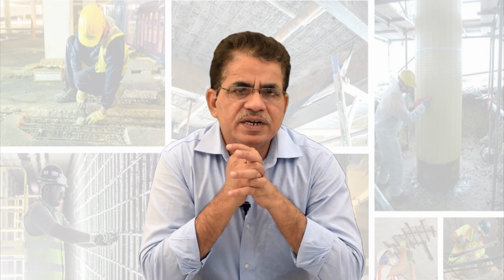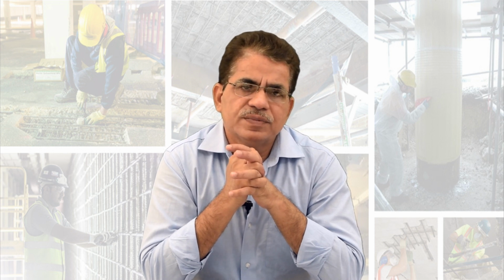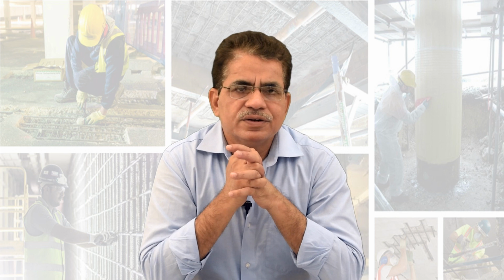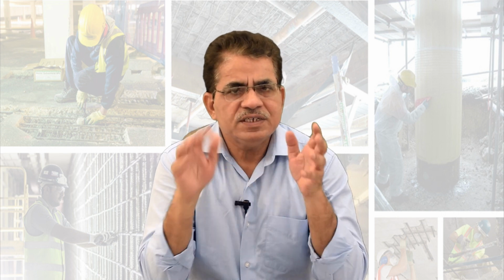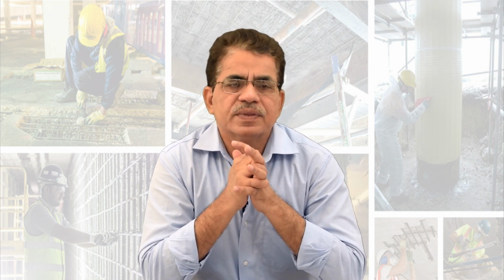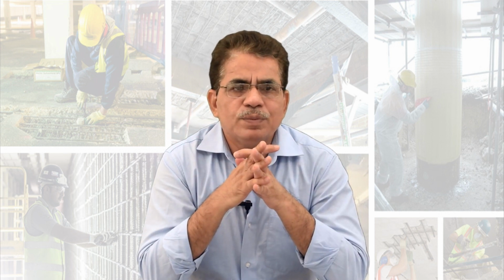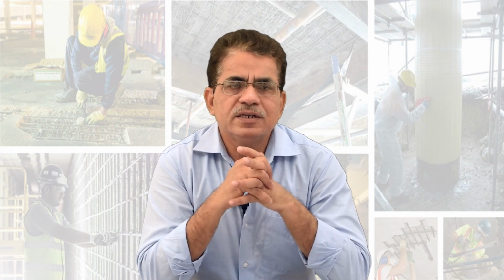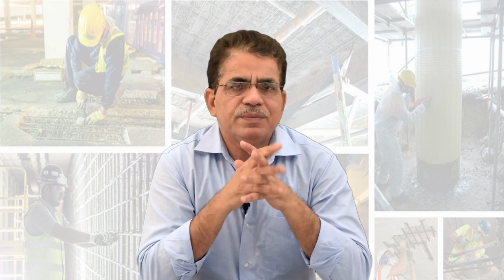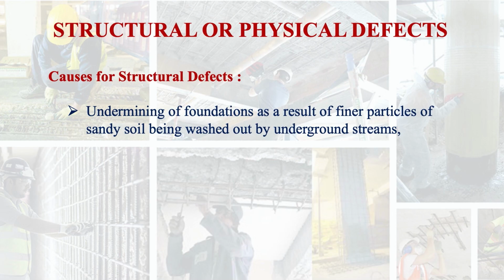If drainage at the site is not proper, then the water which is standing for a long time is certainly going to cause some problems in the building. Then another problem is tunneling. If it is there, then certainly it is going to do some damage to the building. The next is undermining of foundations as a result of finer particles of sandy soil being washed out by underground streams.